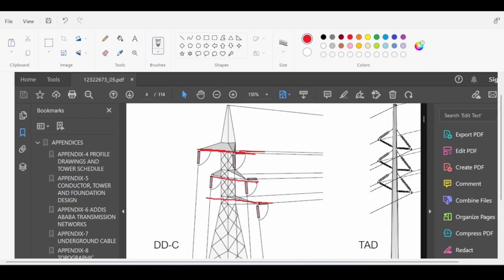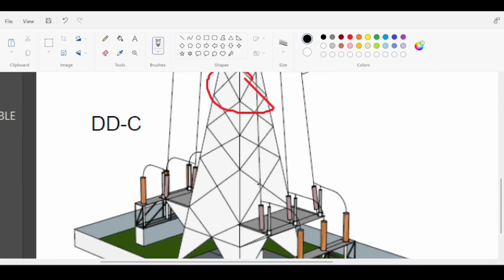You would think, okay, what about those things? Well, those things might be given, and if they are not given, they follow a usual path. They have a certain profile that we are well acquainted with. You see, we usually like to use those lattice trusses to model those transmission towers, and I will talk about this stuff later when we reach that position and how to model that stuff. Basically, if you don't know what the dimensions are, you can check out references, and you will find those dimensions. Of course, your mission is to suggest the sections that those trusses should be made with.